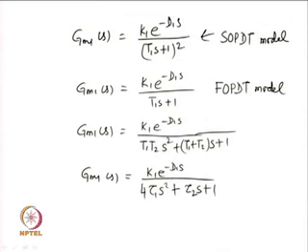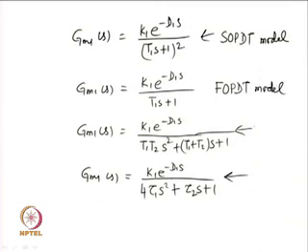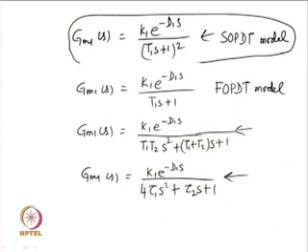That means, this represents the dynamics for an underdamped system, and this represents the dynamics for a second order transfer function model with two distinct poles. So, no doubt the analysis need not be restricted to only the second order plus dead time model we have chosen, rather we can use any sort of model, but there is one limitation.